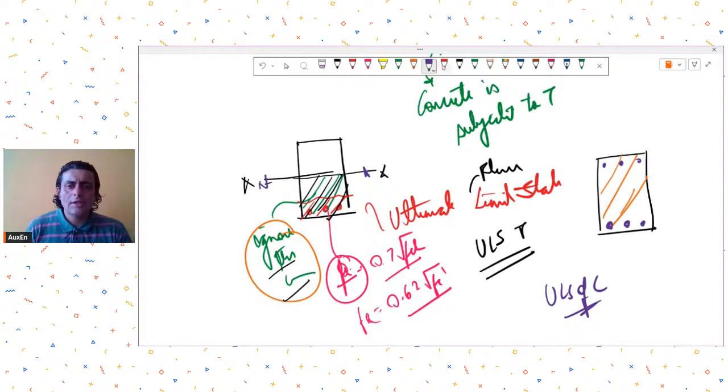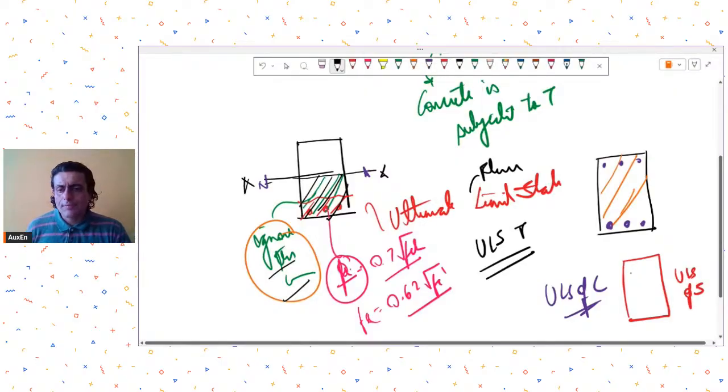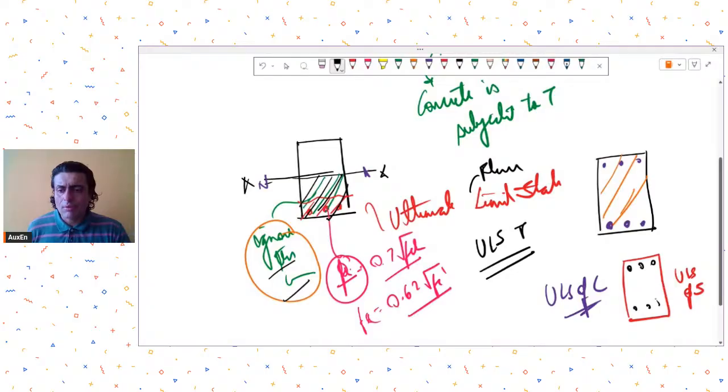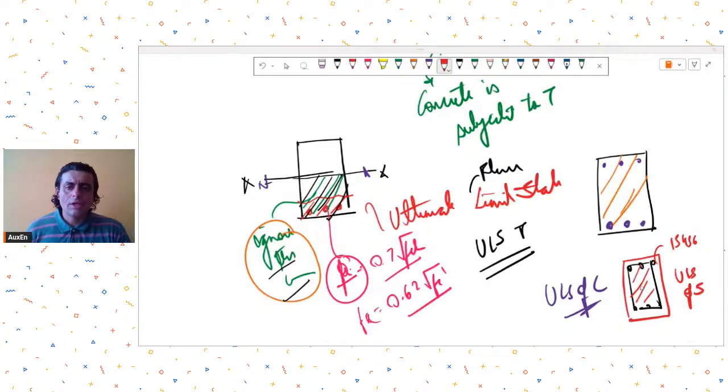When we are discussing ultimate limit state of shear, for shear calculations, it depends on the confinement that is being provided by the reinforcement. If you look at the IS 456 design, we do consider concrete strength to a certain extent. But if you are doing the IS 13920 based design for shear, I don't know if you know it or not, but if you look at the IS 13920 design for shear in beams, and even in column shear design, it tells you to take Vc as 0.